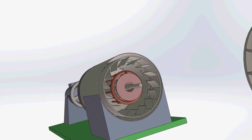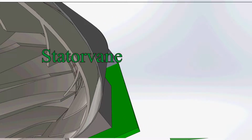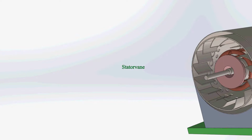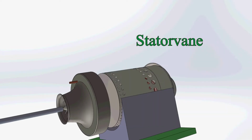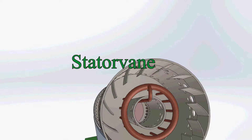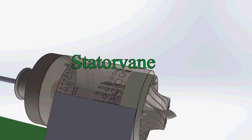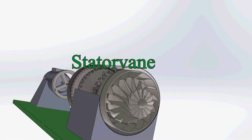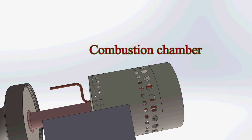The turbine is surrounded by a stator vane where the gas is adjusted to flow tangentially over the turbine. The stator vane is used to convert static pressure into dynamic pressure, or enthalpy to velocity, since increasing the velocity of gas across the turbine has a positive effect of increasing power output. In this project, the stator vane is installed just overhead of the turbine and behind the combustion chamber.